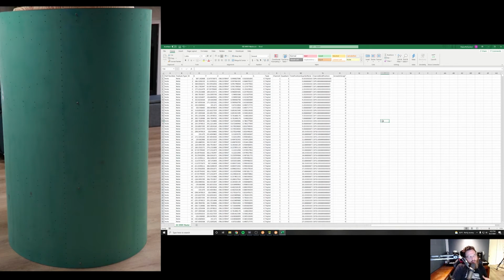Okay, so now you've seen how we can import a CAD model and a corresponding CSV file and overlay it on top of that CAD model. And we need some relevant features in order to align to that CAD model. In this case, obviously the holes that are in the cylinder allow us to align to it. And once we're aligned to it, we can really put anything into that coordinate space that we want to.